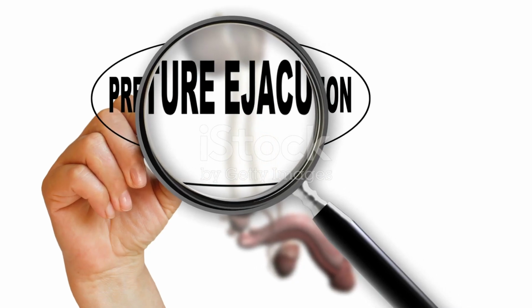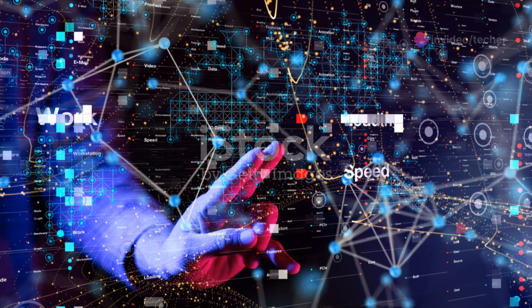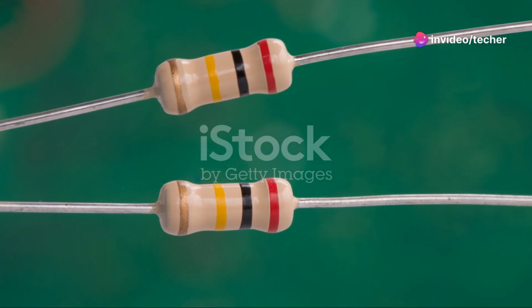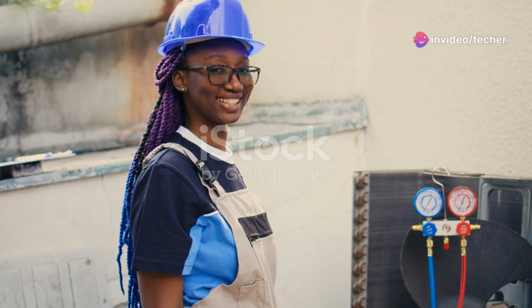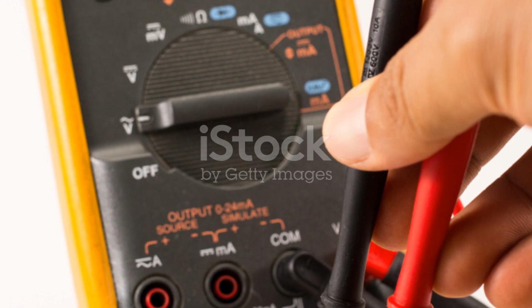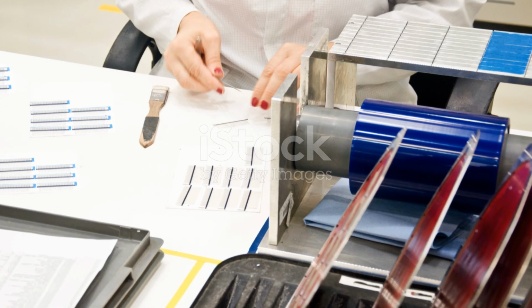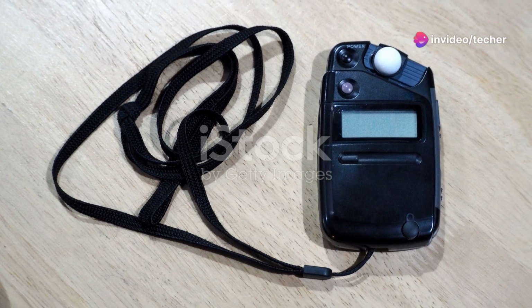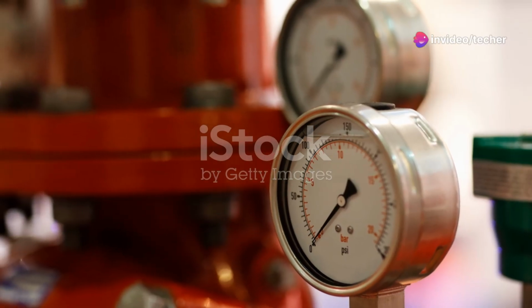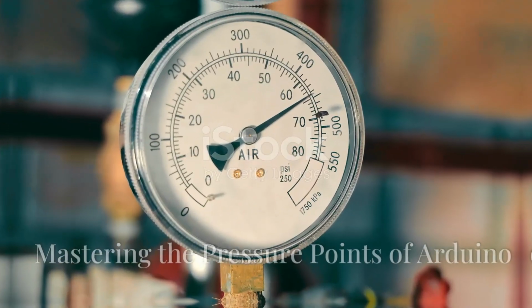Force sensing resistors, FSRs, exhibit a change in resistance based on the applied force. This resistance change can be measured using a voltage divider circuit, where the FSR forms one leg of the divider. The Arduino then reads the voltage across the FSR, which reflects the applied force. Understanding the FSR's resistance range and calibration is essential for interpreting the voltage readings and converting them into force values.